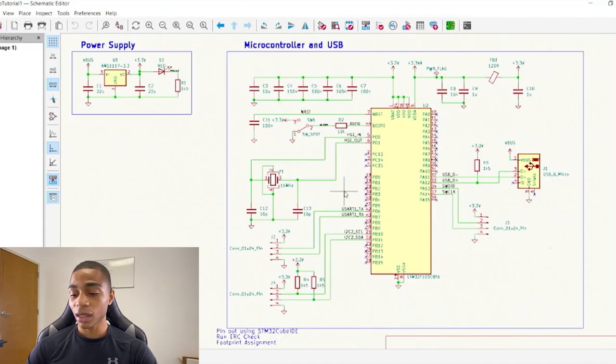So if we take a look here, obviously we have a decoupling capacitor here at C8, but we also have an additional pi filter with the ferrite bead. And because this is more sensitive, we have this ferrite bead to dissipate additional high frequency noise in the form of heat. So that's why our VBAT, VDD, and VDDA are separated.